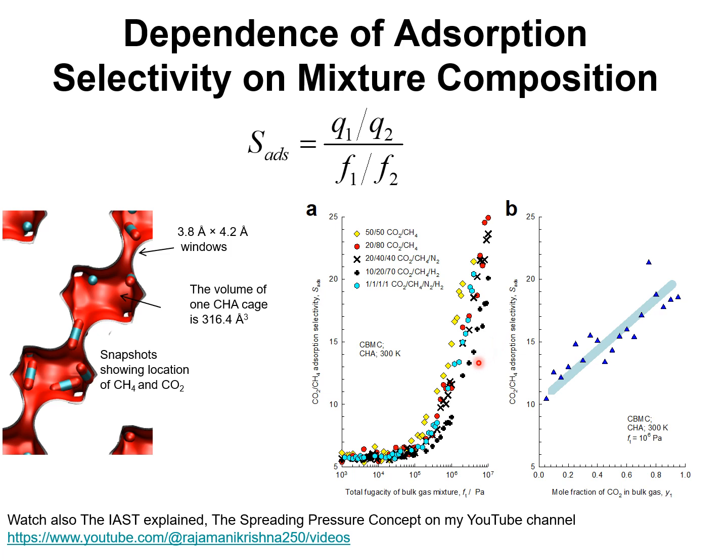The pluses represent the CO2/methane selectivities in a ternary mixture of CO2, methane and hydrogen in the proportion 10-20-70. The cyan colored hexagons are the data on the CO2/methane selectivities in a quaternary mixture of CO2, methane, nitrogen and hydrogen in the proportion 1-1-1. We note that at any given total fugacity of the bulk gas phase, Ft, the selectivity depends on the mixture composition.